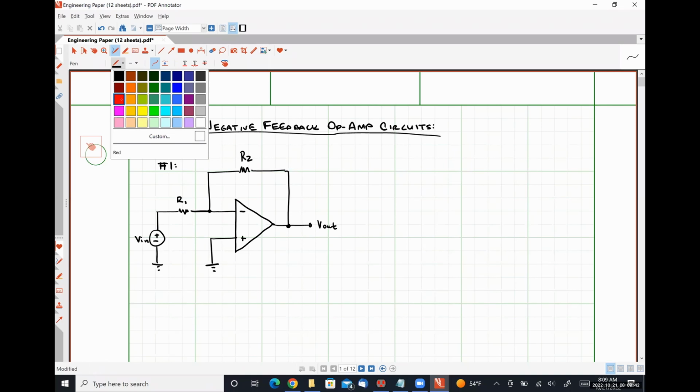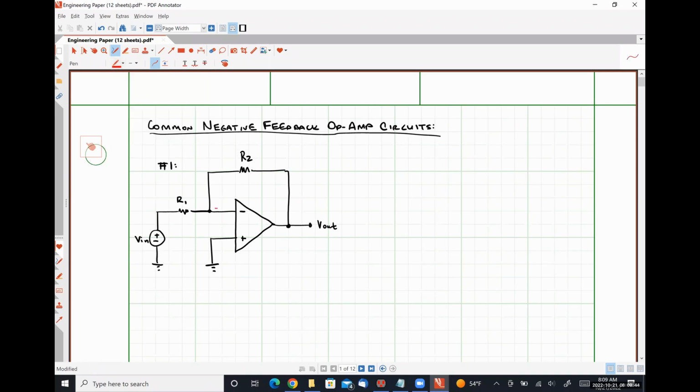All right. So our first step is always to apply op amp rule number one and observe that no current can flow into either input terminal. And then we determine what our voltage is at our non-inverting input terminal, which by inspection here, we can easily see is 0 volts.